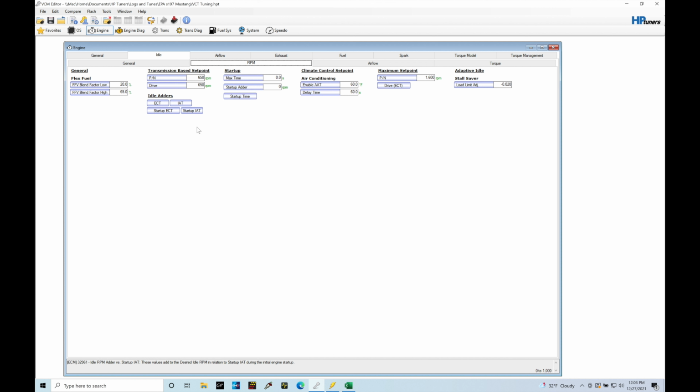In order to vary the amount of torque output out of the engine, we can vary the amount of airflow, we can vary the amount of spark timing, and/or we can vary the amount of fuel that we deliver to the engine. When we're talking about idle conditions, we're going to be at stoichiometric, or a 1.0 lambda target in our closed loop operation. So we'll assume that the fuel is taken out of the equation here because we're not going to be altering the fuel in terms of the target and what we deliver to the engine. We're going to be at a consistent amount of fuel being delivered, so we can essentially remove fuel as a means to alter the engine's torque production.